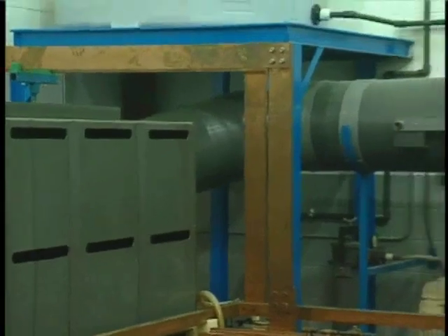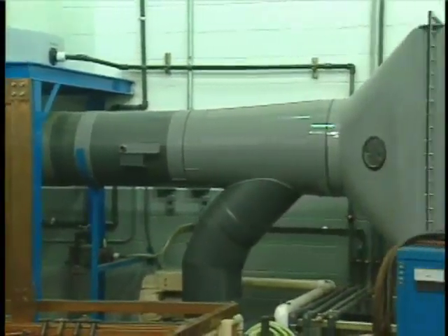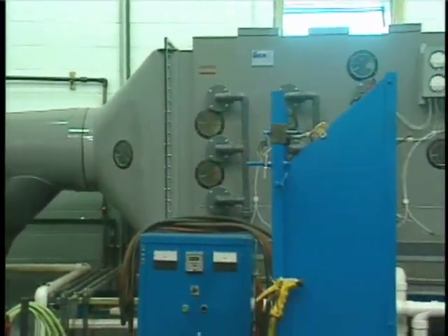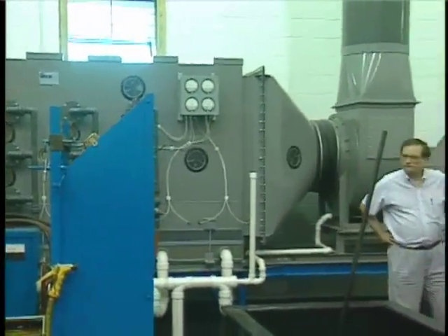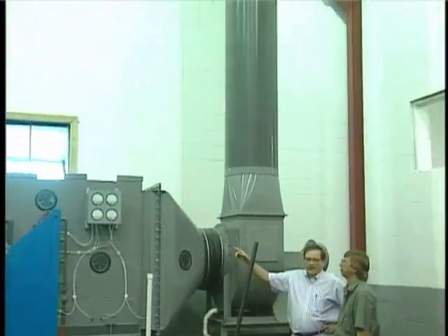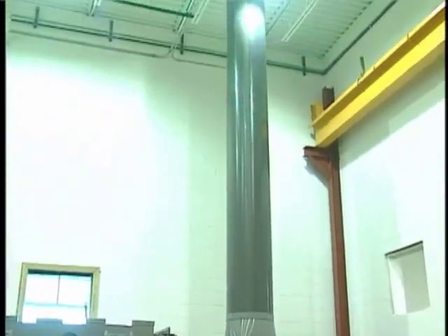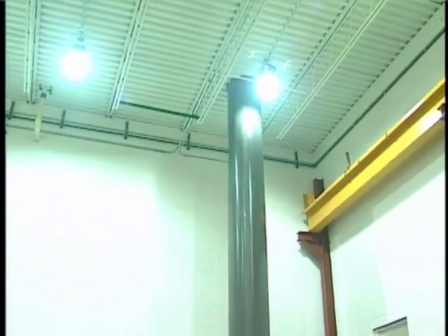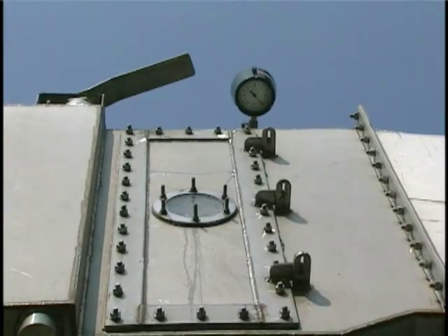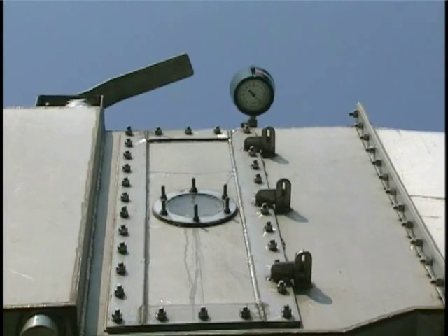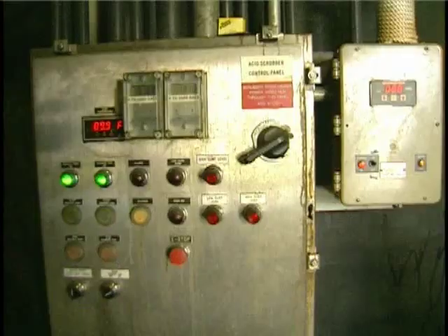Perhaps the best indicator of adequate gas-liquid contact is the difference in temperature between the inlet and outlet of the scrubber. If that temperature difference has decreased, it is likely that the collection efficiency has also gone down. For example, a higher than normal temperature at the outlet of a scrubber may indicate a decreased liquid flow rate.